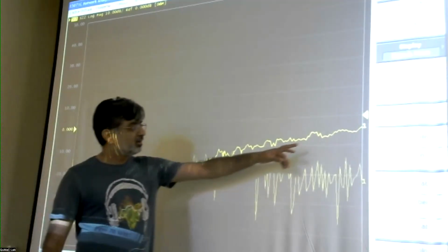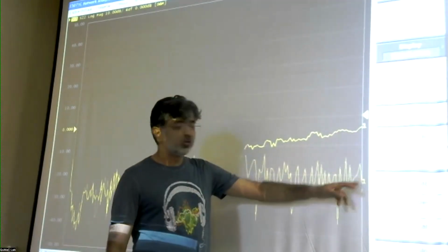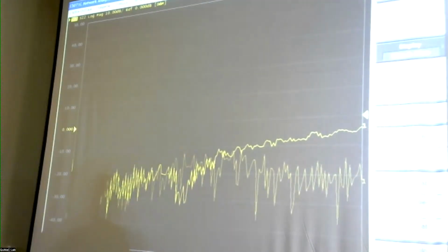Remember here, it's going to measure the total reflection, which could happen from anywhere. So S11 means that the other port is terminated with 50 ohms, and it's measuring whatever the power is coming back. Now the port is terminated with 50 ohms, but we are saying that maybe the connector is bad. So you could have a reflection right at this point, or you could have a reflection right at that point. Let's for the moment assume that the cable itself is fine. So these are the 2 points of reflection you can have.